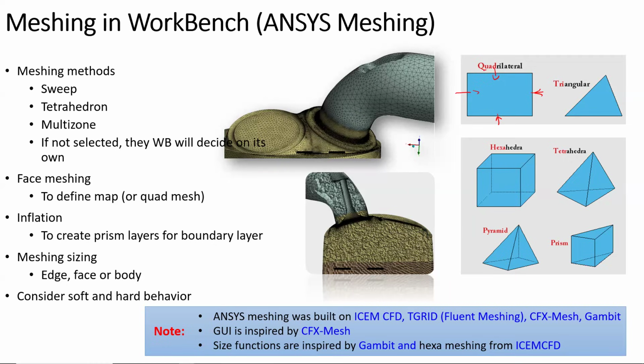Diffusion means the solution will be diffusing, like viscosity. If you put ink in water, it will diffuse to the sides. So this will be more diffusive in a triangular mesh. In a quad mesh, the solution will not diffuse, and it will be contained to its particular value in that cell. A triangle has three faces, so it will get information from only three sides.